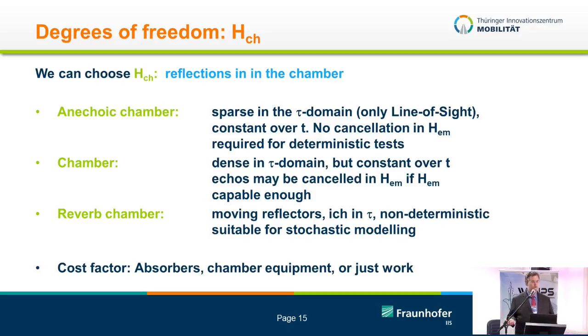If you want to do stochastic modeling, a common and standard approach is actually the reverberation chamber. The reverberation chamber is a, well, partly anechoic chamber, where you have some structure moving inside, which gives you some moving reflections, which under certain conditions can be shown to be stochastically similar to a practical channel on the outside. So that's what is used to test fading channels without much other hardware. It's a very cheap system, however, it is only stochastic.